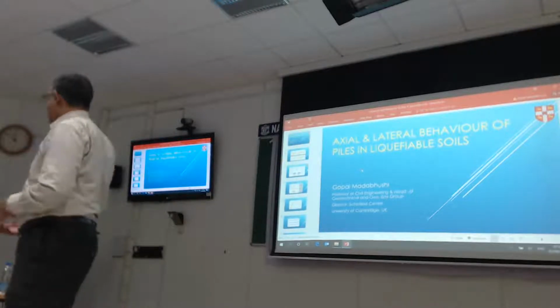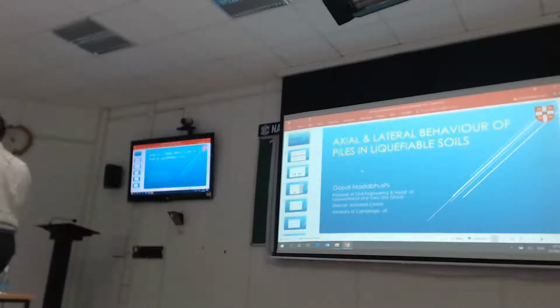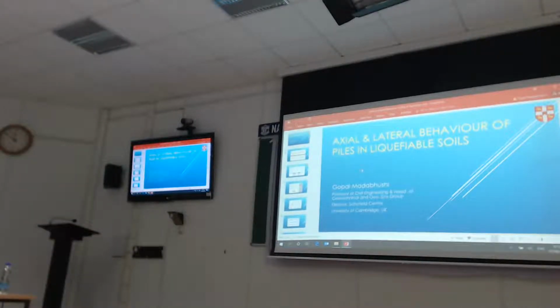So that's of course not considering the soil effects, but normally you would expect piles like what recent tests have tested, which are half a meter diameter piles, so they are fairly flexible. If you have a 1 meter diameter pile, a pile with steel casing outside, those will have much higher buckling loads, and the problem will disappear.